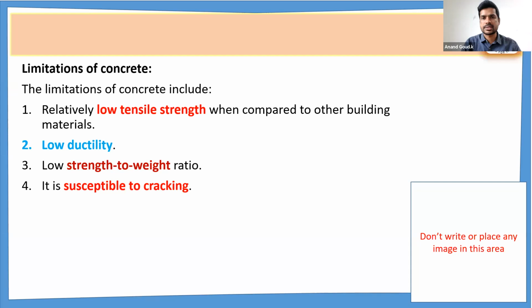Limitations of concrete. That means disadvantages of concrete. Okay, so every material will be having some positives and some negatives. So like that, this concrete is also having some limitations. The first one is low tensile strength. Okay, so as we have discussed in the previous slide,